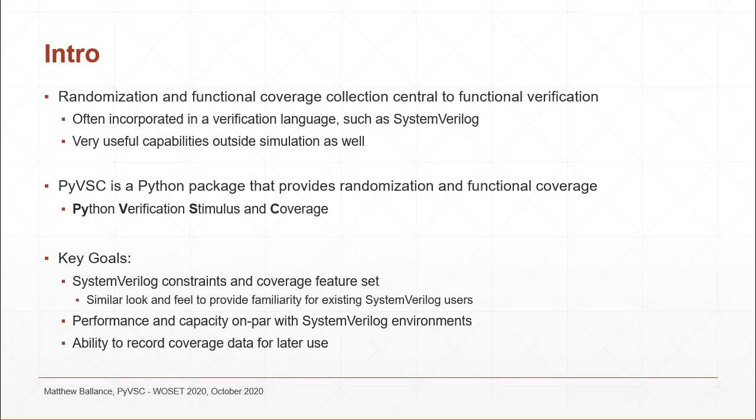PyVSC is a Python package that provides these capabilities. PyVSC stands for Python Verification, Stimulus, and Coverage. The key goals of the PyVSC library are really to bring the SystemVerilog look and feel to Python constraints and functional coverage. So in other words, have as similar a look and feel as possible to SystemVerilog, and as similar a feature set as possible to what SystemVerilog provides.